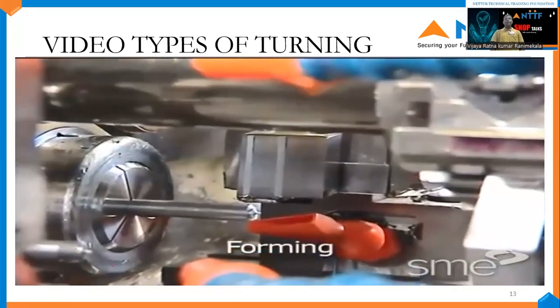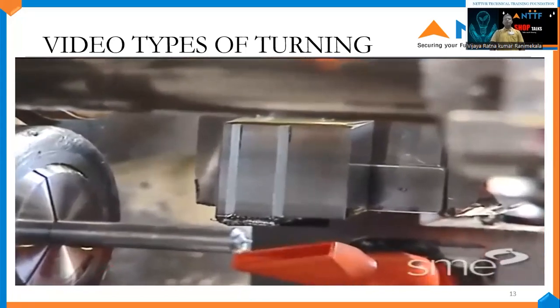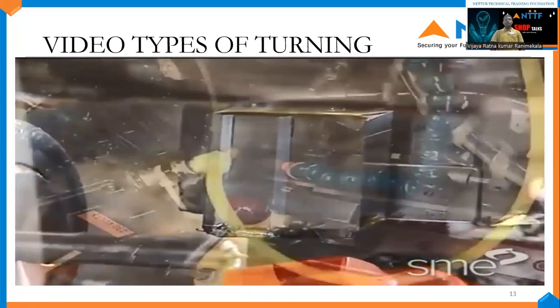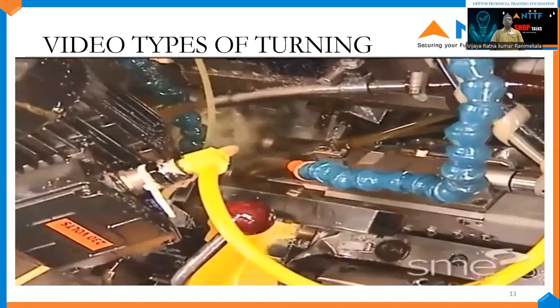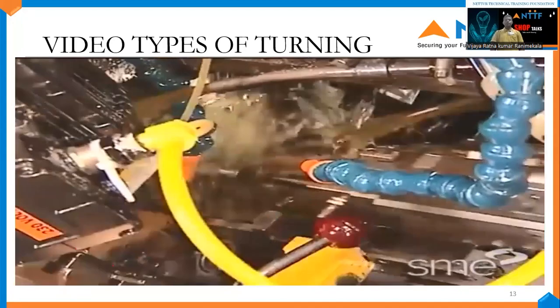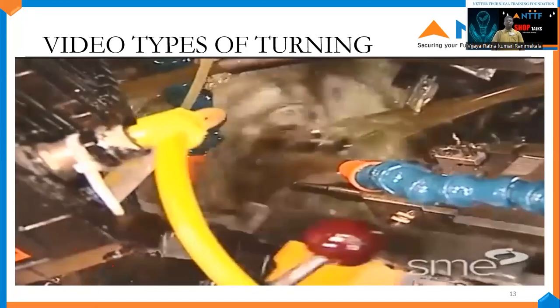Forming is another alternative for generating complicated shapes. The cutting tool having the desired form or geometry is advanced perpendicular to the axis of rotation, reproducing the tool shape in the workpiece. Forming is commonly performed on automatic screw machines.